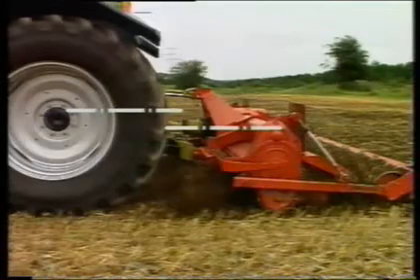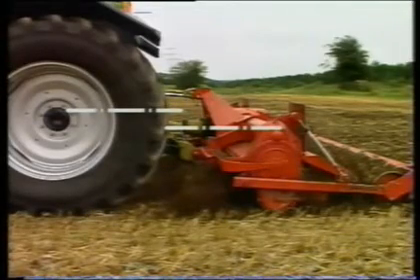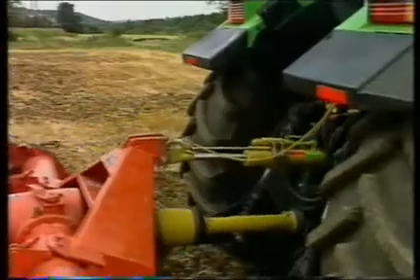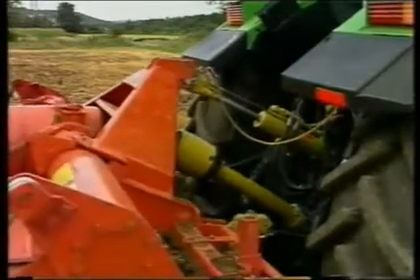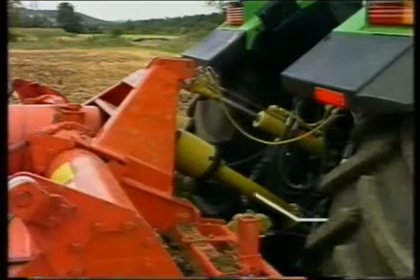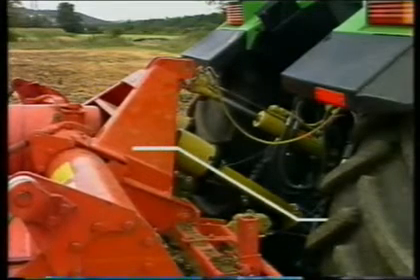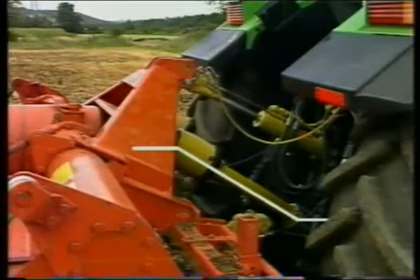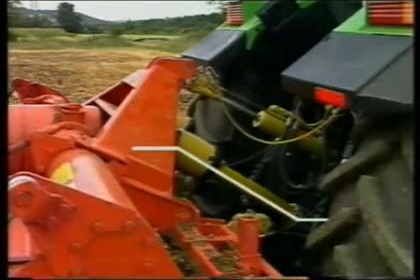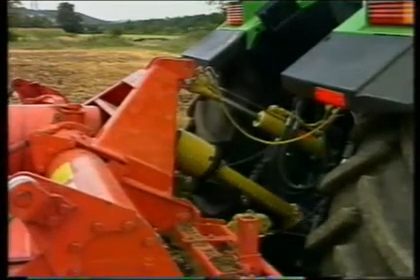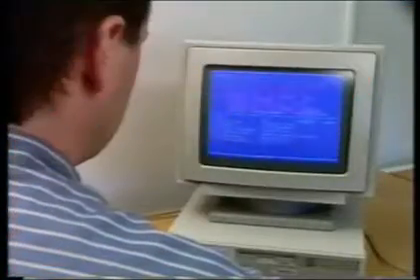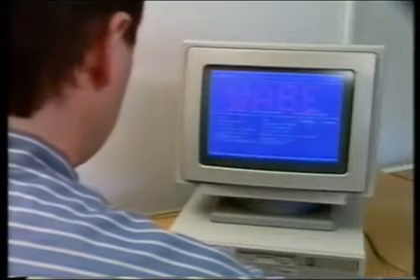In the case of faulty attachment, for example excessively short and excessively high attachment of the top link, an exact Z-bend is no longer possible during lifting of the implement. 7% velocity variation, which can be considered as the damage limit at a PTO shaft speed of 540 RPM, is already exceeded after lifting the implement slightly.